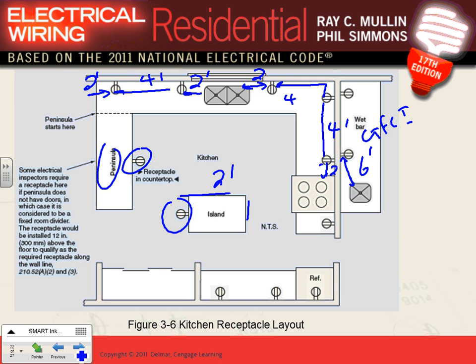Any question about laying out these receptacles? You guys are going to have the same countertop. You're going to lay out the receptacle. These are easy. This is a 2 by 4 rule here. This one, if it's 2 by 1, 2 feet by 1 foot, 1 receptacle. 2 by 1 or more, 1 receptacle. This area, guys, suppose this is a 1 foot space right here. Can you see that? 1 foot space. What do you need to do? 1 receptacle. 6 inches, it's up to you. 1 foot or more, 1 receptacle.